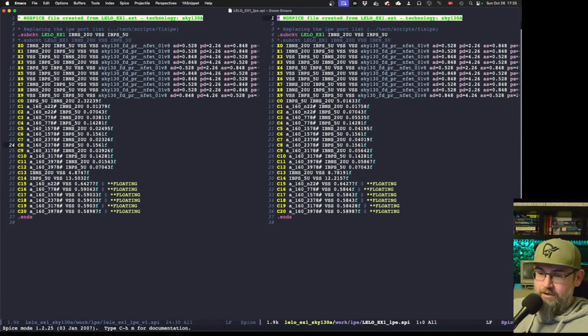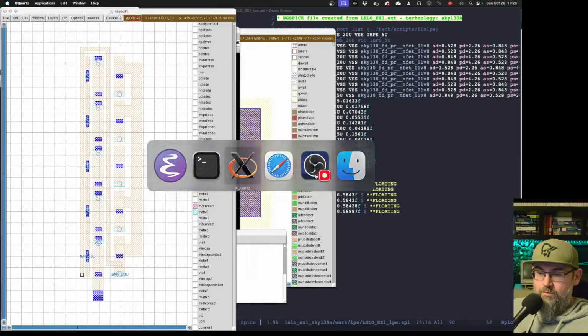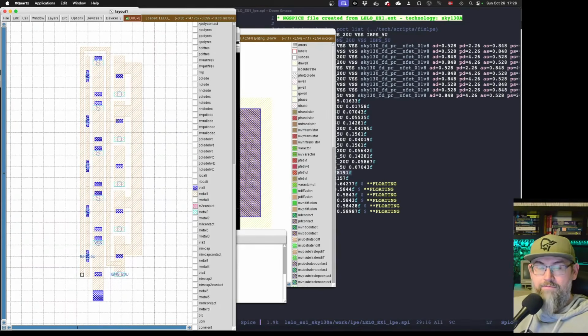Okay. So now you can see that I've doubled the parasitic capacitance on the right side here between my output net and my input net. And I've actually reduced the capacitance to ground, and I've almost doubled the capacitance from the output net to ground. So the way you do the layout affects to a significant degree these parasitics, and you have to think about that while you do a layout, especially for coupling between sensitive nets and what we call aggressors, like clocks and stuff like that.